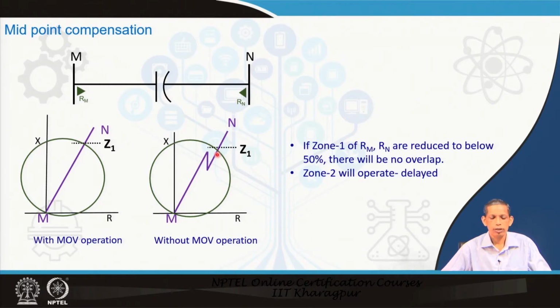So, what we say here is that in this case there may be an overreach phenomenon, with the presence of the capacitor and without the capacitor. So, in this kind of environment we can have a reduction in the zone 1 setting, that is one approach. The other approach, however, is that the corresponding compensation becomes very large, that becomes difficult, and in case the capacitor is, let us say, 70%, then 50% minus 70% is minus 20%, again this 30% that becomes 0 kind of thing.